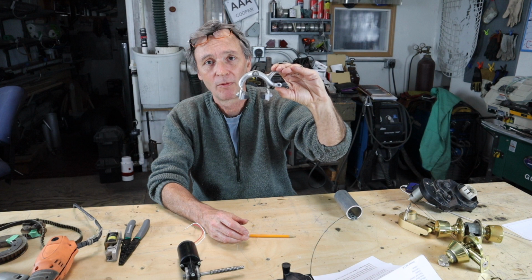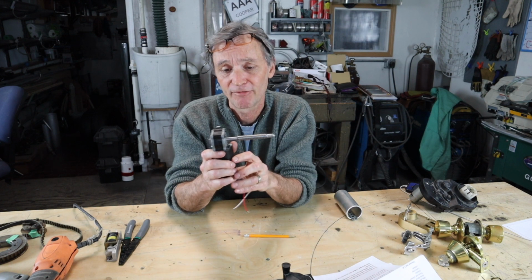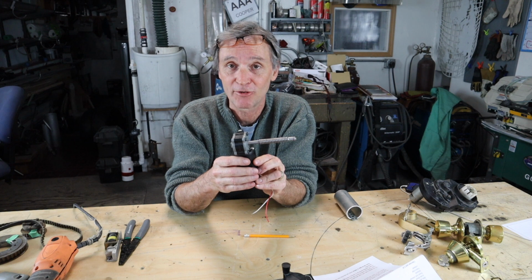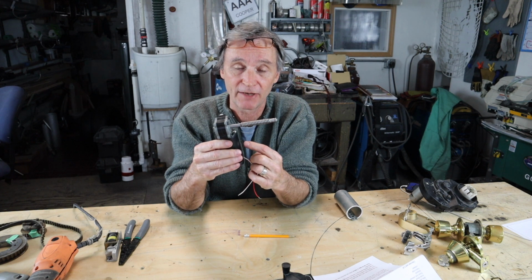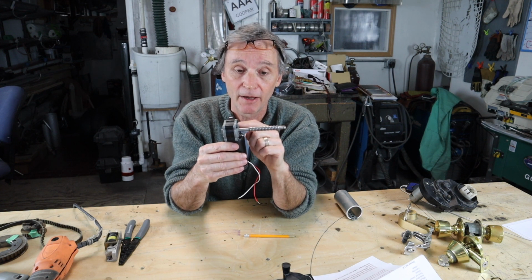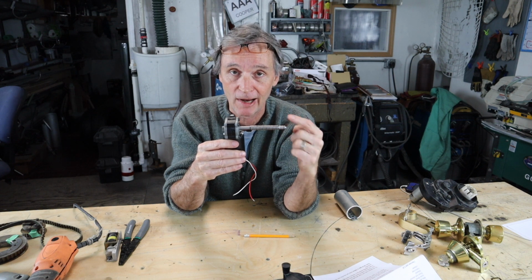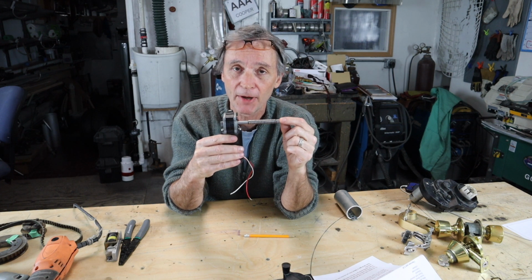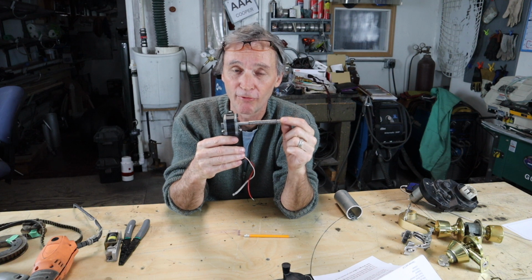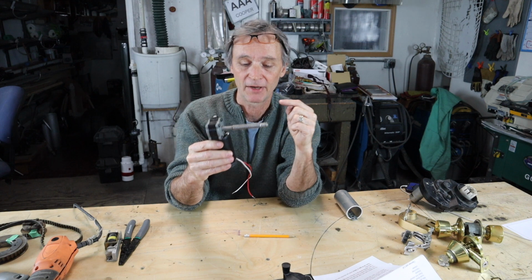This is a side pull brake. And every time you drive a car, there are possibly hundreds of different mechanisms in the car, from the door handle to get you in, the electric window going up and down. If you're lucky enough to have electric seats, this, for example, is a seat actuator, turns rotary motion from the electric motor via a worm gear into a lead screw turning around, but going much more slowly and with a lot more force than this motor was turning. So that's a very common mechanism.